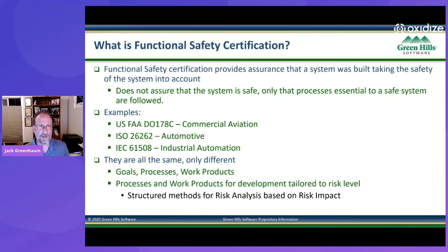For example, an instrument cluster in an automobile: a safe state for a graphical instrument cluster is actually blank. The safety rules there say it's better to show no information to the driver than to show incorrect information to the driver. Now that is considered a middle-low safety level.